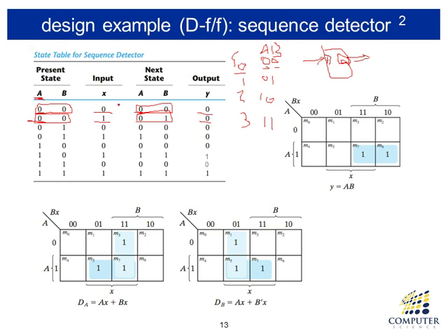So to make this state table, you need to apply on D those values. If you apply those values on input D, that value will appear on Q on the next clock tick.